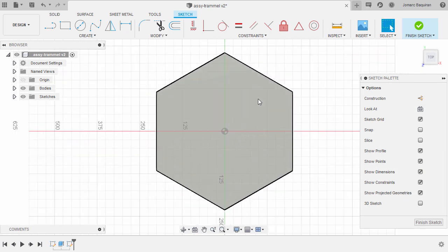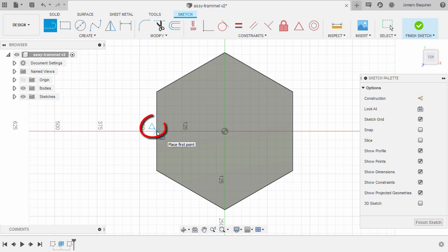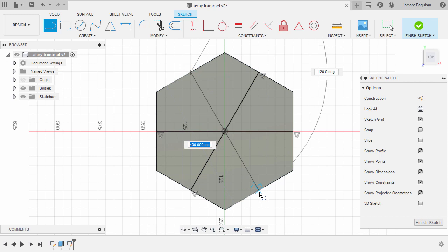Let's grab our line tool, hitting L. Let's drop our first point at the midpoint of this vertical edge. So notice the blue triangle indicating it's a midpoint. Left click here, moving to the right, double left click, moving here, left click, locating the midpoint, left click here, and left click here. In addition, I want you to notice the placement of the midpoints.